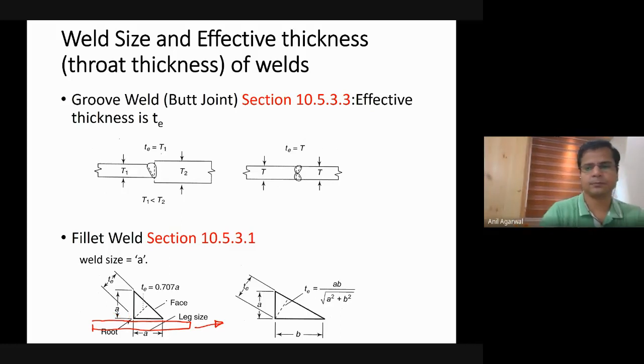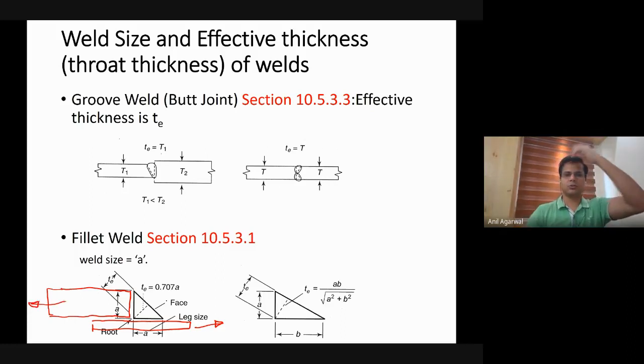Let's say this is another plate and then it is being pulled this way. Now it is obvious, right? So you may have two plates with a lap connection and then they are being pulled in different directions. In this kind of situation, the fillet weld will not be under pure shear. It will be a combination of shear and tension. So either way, just keep in mind that these two stress states exist for a fillet weld.